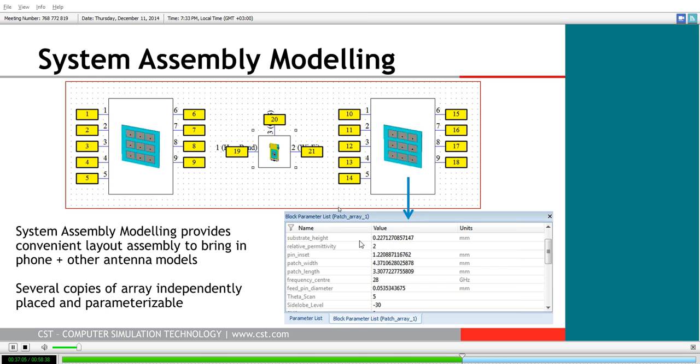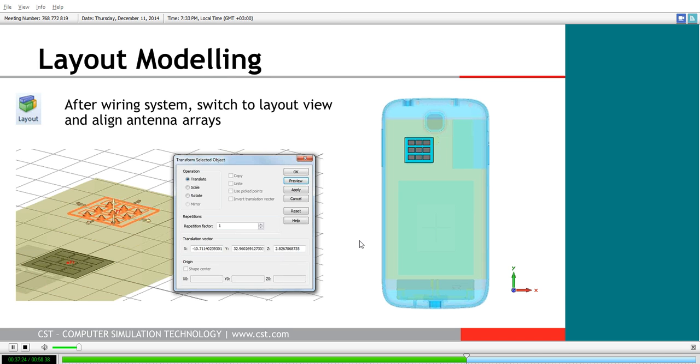Now, because we're going to be aligning these things, we're basically mounting them structurally. There's no electrical connection beyond those we'll form with 3D placement. All we need to do is wire in external Design Studio ports to each of the wire terminals on these Microwave Studio blocks to make the system complete. After we have our design canvas taken care of, we need to define the relative alignment, how these different 3D models that we're bringing in are oriented to one another. To do this, we can go into the Layout tool, which will bring up a 3D modeler window very consistent with what you're used to in Microwave Studio that allows you to then align your different geometries together such that they reflect the installed performance.